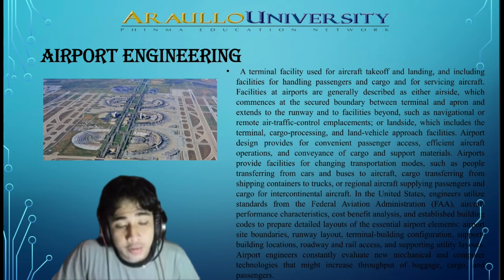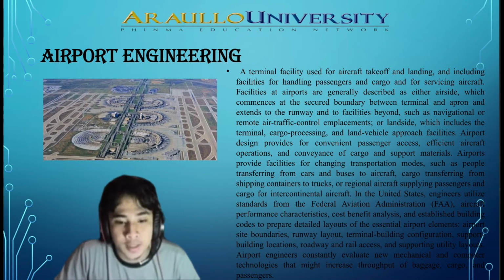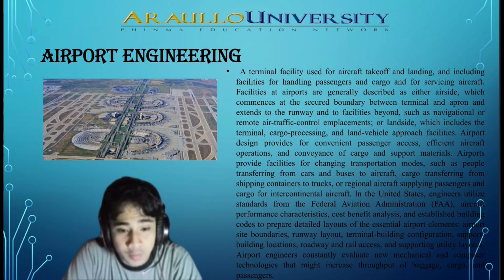While airport engineering, an airport is a terminal facility used for aircraft takeoff and landing, and including facilities for handling passengers and cargo and for servicing aircraft. Facilities at airports are generally described as either airside, which commences at the secured boundary between terminal and apron and extends to the runway and to the facilities beyond, such as navigational or remote air traffic control emplacements, or landside, which includes the terminal, cargo processing, and land vehicle approach facilities.